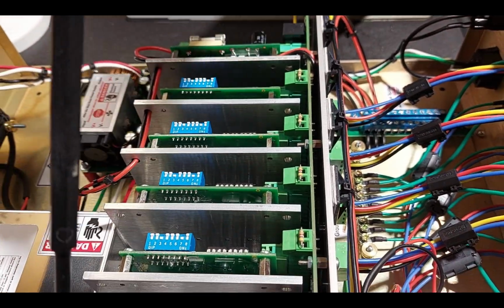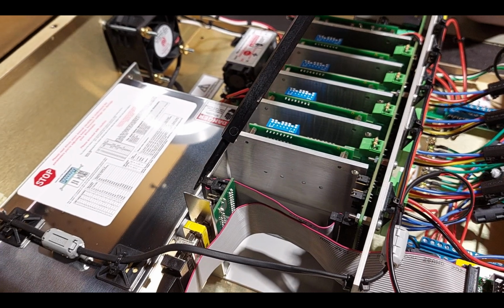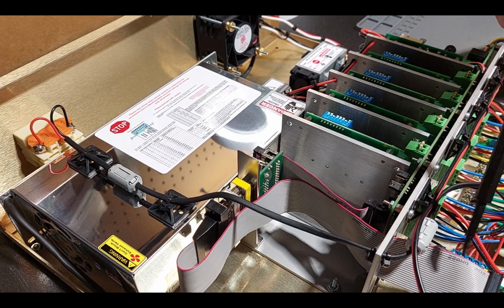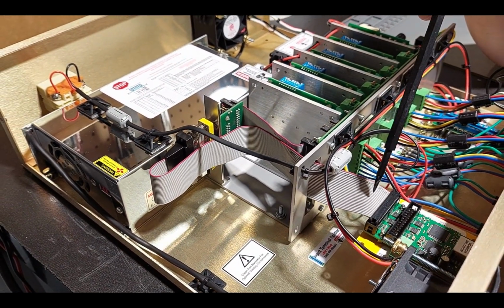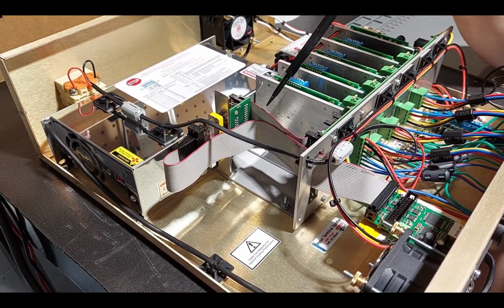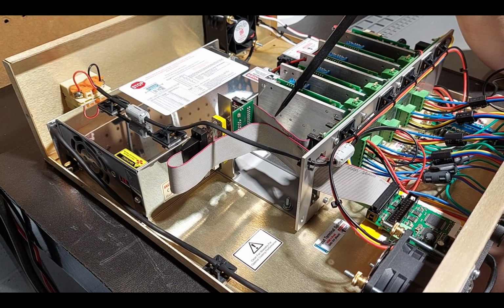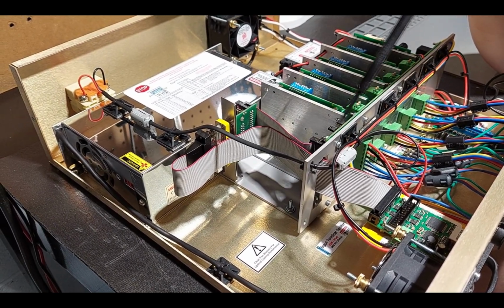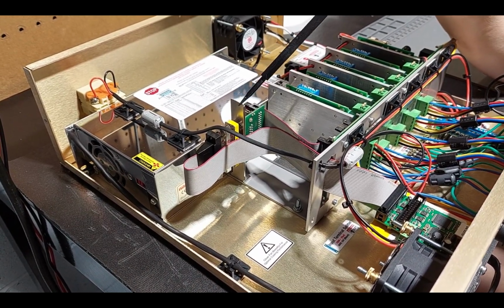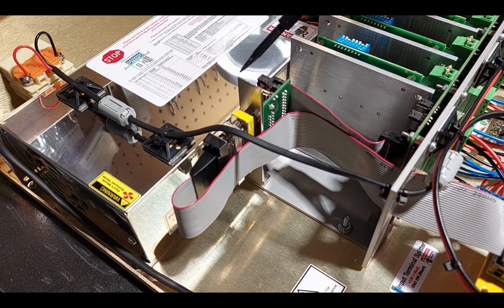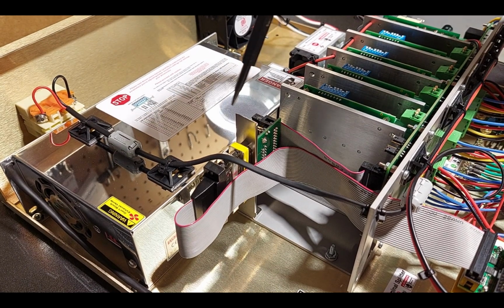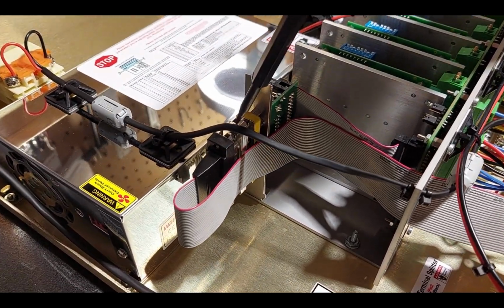And then coming over here, I wanted to discuss this because what I used was a PC mounting bracket for our DB25. Now, why did I do that? I did that because this cable, in order to make it fit appropriately where we didn't have to bundle up our ribbon cable, which again is not best practice because ribbon cables are susceptible to data corruption if they have a lot of sharp bends. You can see what I did. I just used the PC spring steel mounting bracket, made sure that it could clear the top of the enclosure, and it mounts everything absolutely beautiful and includes, of course, an EMI filter right here.